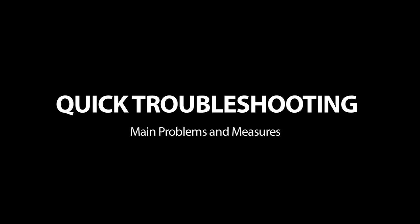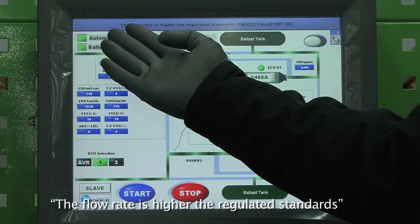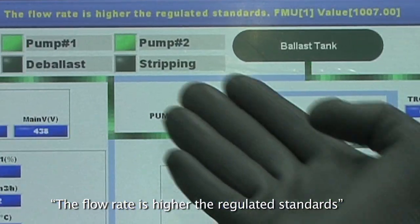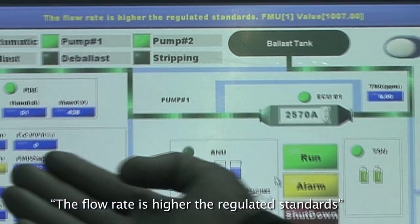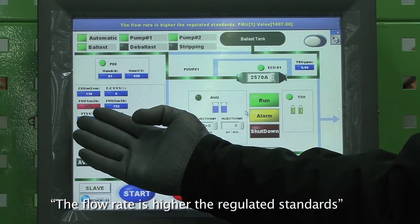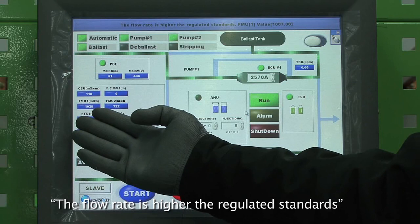Quick troubleshooting. 1. Main problems and measures. Problem: ECS shuts down 1 minute after the alarm message "The flow rate is higher than the regulated standard" appears. Reason: when flow rate is above the normal range. Normal range: 10% to 110% of pump capacity.